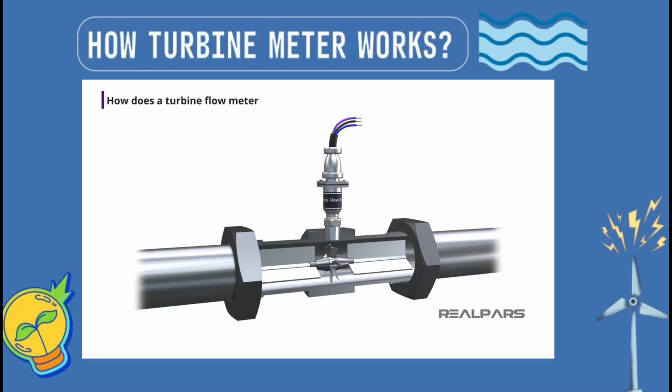First of all, let's talk about how a turbine flow meter works. A turbine flow meter is inserted in a pipe directly in the flow path. The mechanical part of the turbine flow meter has a turbine rotor placed in the path of a flowing stream. The only moving part of the turbine meter is the mechanical rotor. The rotational speed of the rotor depends upon the flow velocity. The rotor blades are usually made of stainless steel.